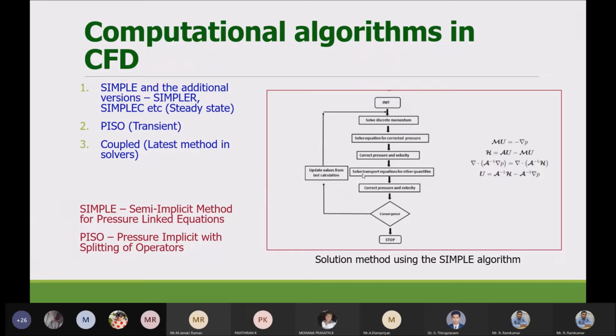But if you just begin heating, what will happen is its temperature will slowly start to rise, and then it will go and stabilize. So if this rising portion is your interest, then you have to perform something called a transient simulation, meaning it changes with time. So what does the SIMPLE algorithm do? Remember in the starting, I said momentum, mass transport, and then energy transport. Let's get into that. So there is something called a momentum equation, that is our Navier-Stokes equation.